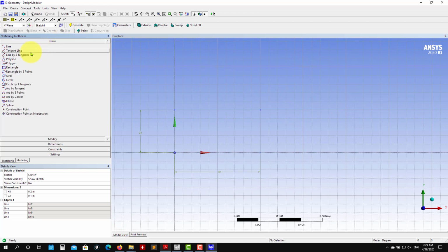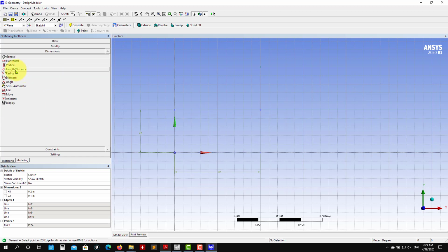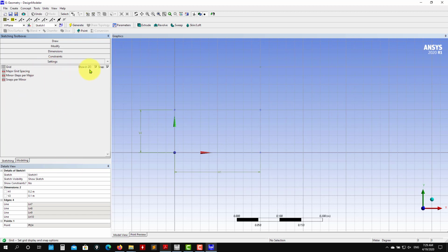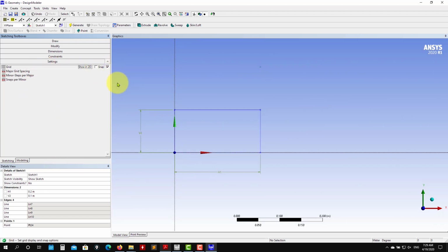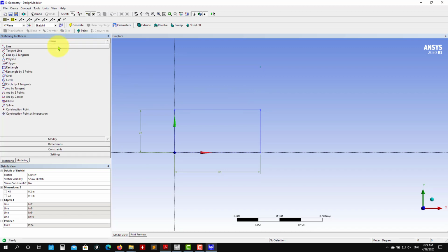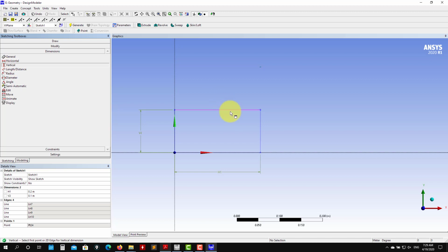Let's create a construction point. I will put a point here. That one I know is 1, but remember to always add your dimensions. Here I don't see well, so I will hide the grid, and leave this snap. It's a vertical, from here to here. You select two with control, set the distance to 0.1. This will be our center for the circle.